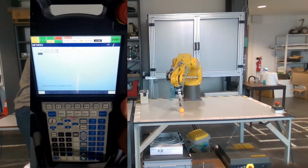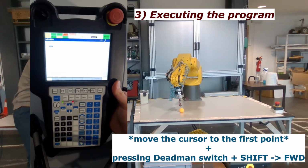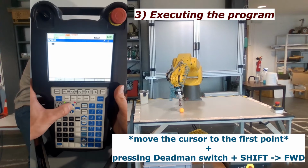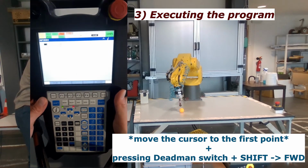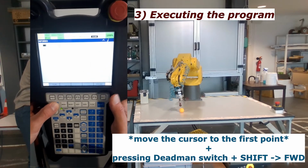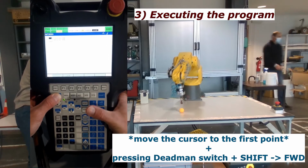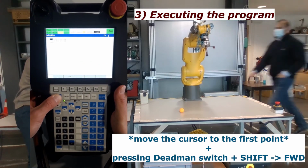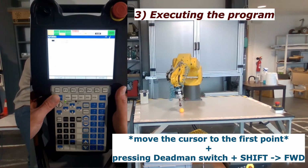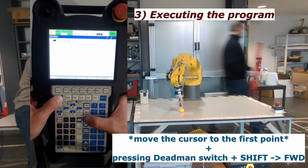With these two different points recorded, we can already run the program to see if the robot will behave as it is expected. For executing the program, we need to move the cursor until the line where we want to start. In this case, I will move the cursor to the first line of the program so that the robot executes all the script. For running, we have to press and hold deadman switch button and the shift key simultaneously, and then press the forward key just to start. The forward key just need to be pressed once.